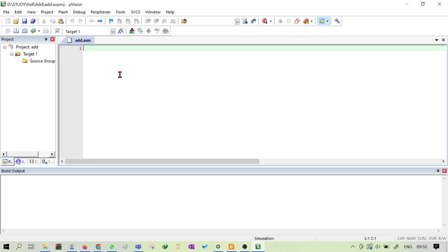Next we want to see that in this device there are different ports defined. You can go to the peripherals, and there will be ports coming out. Once we are writing the program, we are providing some input from a particular port, and then we are going to save it to a particular location. So starting with, we will be writing org 00h, capital H or small h.